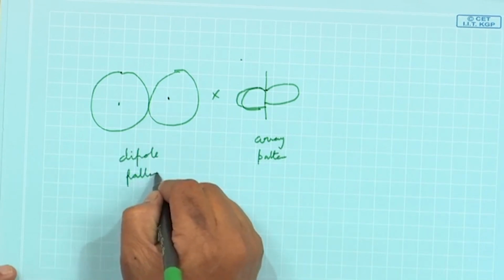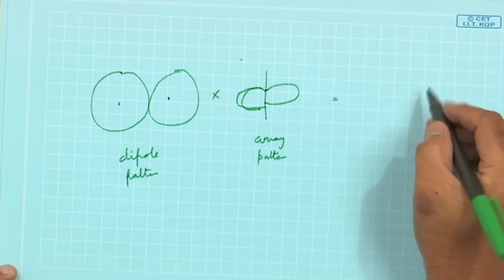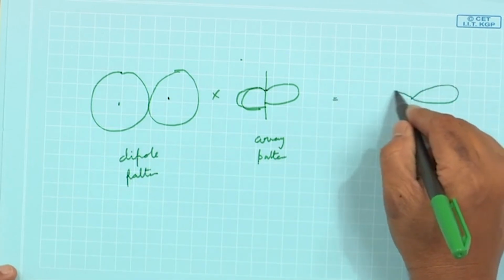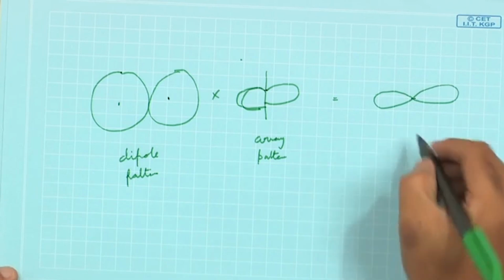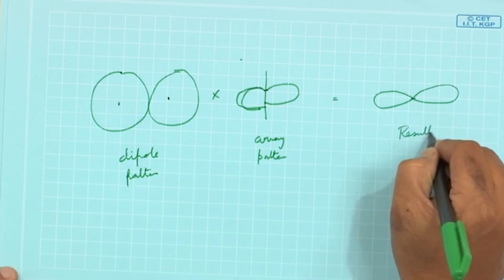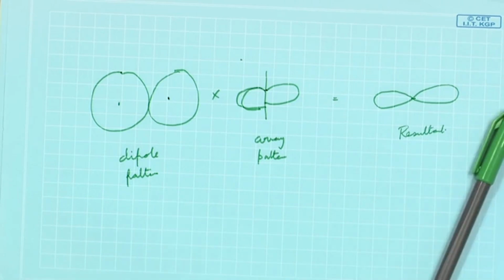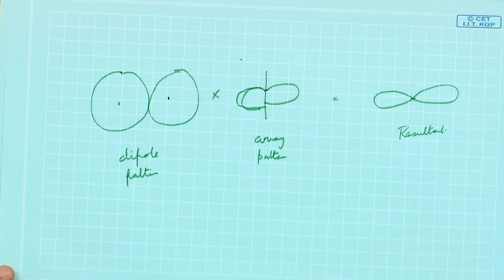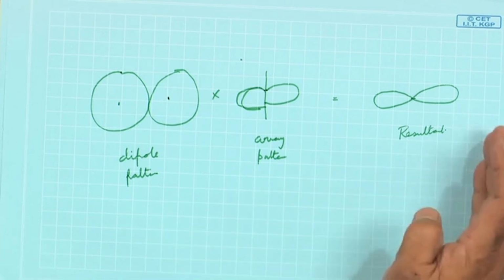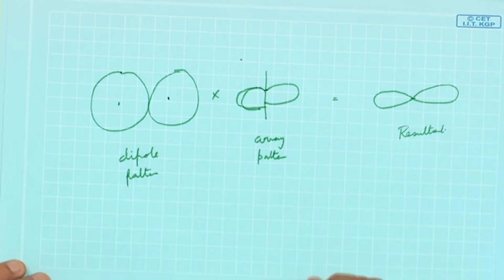So, pattern multiplication will give that I will have the resultant pattern like this. So, here both E and H plane patterns are governed by array pattern, and if n is large, the element pattern of half wave dipole has little effect here. So, mainly for Endfire arrays, the resultant pattern is governed by the Endfire array.